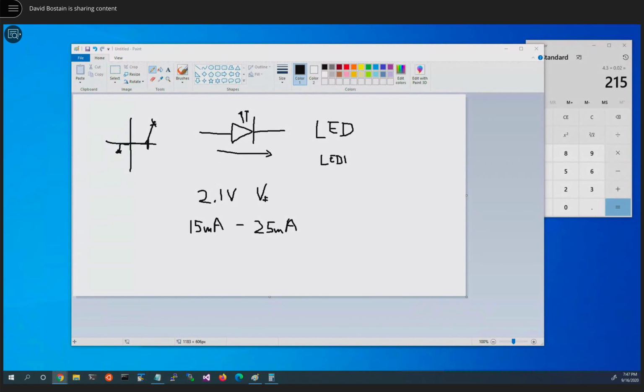Okay. You guys either talk to the people who were in class last night who got it wrong, or you guys are smart. And we'll go with smart for now till you prove otherwise. I would pick a number halfway between. Halfway between means I would normally design using 20 milliamps as my assumed current, because I know the resistor that I use will probably not really be the value I compute. And I have to have some tolerance above and below in order to avoid problems.